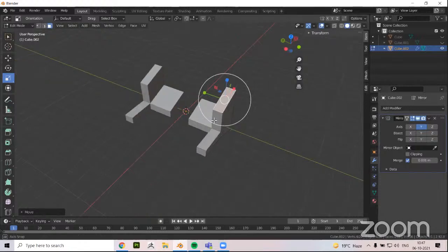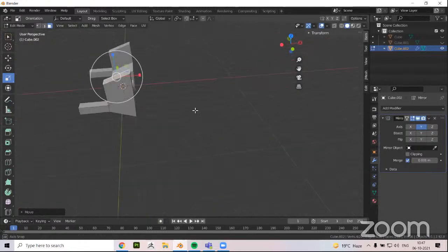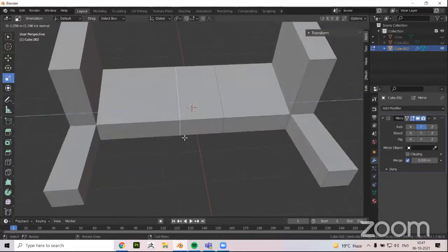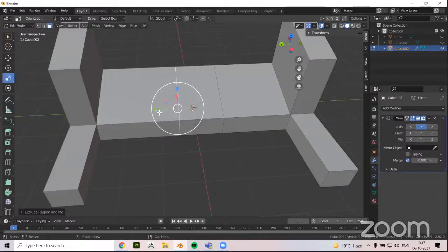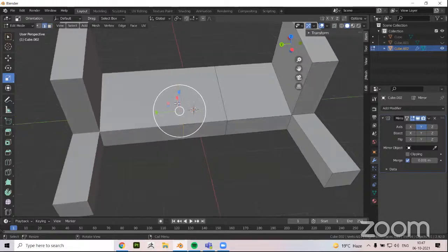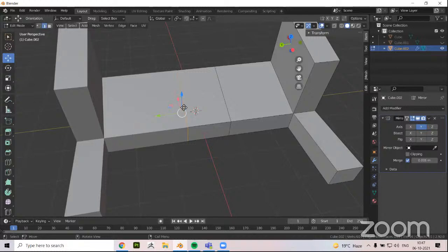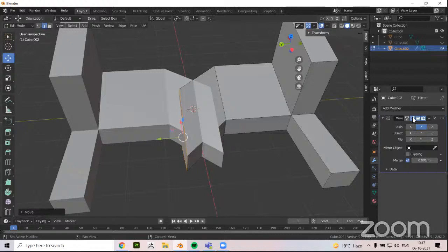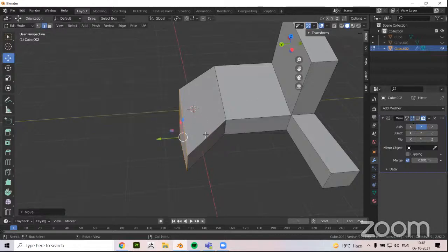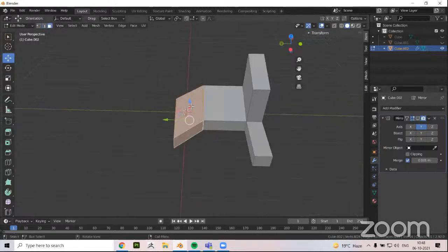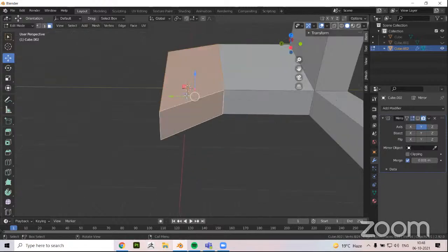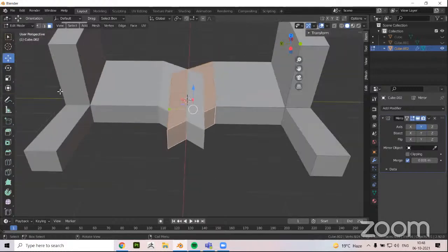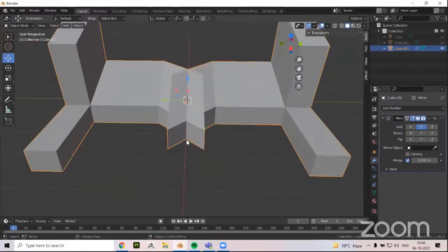side. And suppose if I'm creating a shape from this side and I'm crossing my origin, which is the center point, then whatever mirror I have created would also happen on the other side. So suppose right now I've crossed the origin, I have this shape and I want to move it. We can see the moment I'm moving this face, this is my original shape where this whole set of faces are crossing the center point, the origin, which is indicated by this point. And the moment this modifier is on, we can see that the same thing is being mirrored as well, and it's coming out from the opposite side.